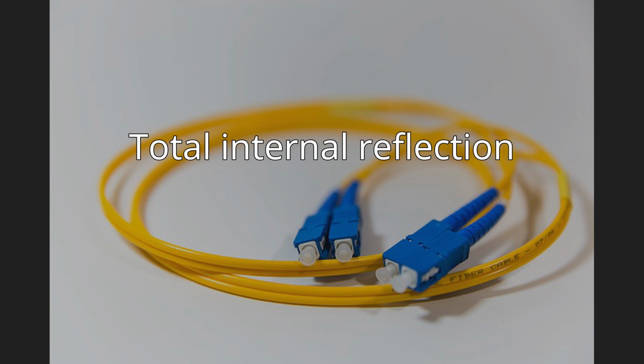Light travels through the fiber core, bouncing back and forth off the boundary between the core and cladding. Because the light must strike the boundary with an angle greater than the critical angle, only light that enters the fiber within a certain range of angles can travel down the fiber without leaking out. This range of angles is called the acceptance cone of the fiber. There is a maximum angle from the fiber axis at which light may enter the fiber, so the sine of this maximum angle is the numerical aperture, NA, of the fiber.